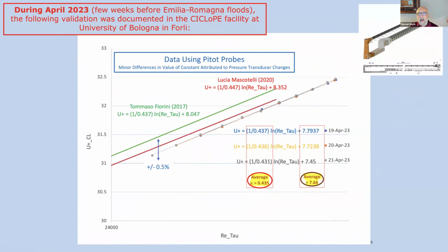Okay, now when you go to the Superpipe, and you can see how long it is, and I showed you that picture already. You can follow the centerline velocity, and it takes a little explanation, but the centerline velocity plotted on log law gives you kappa also.